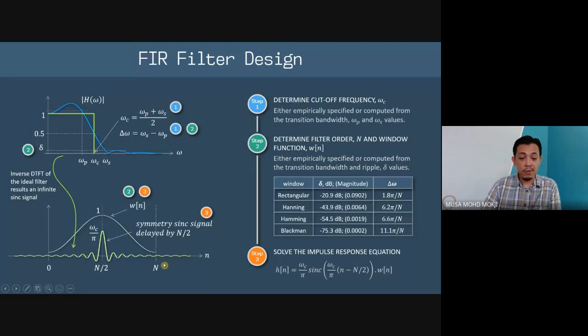So how do we solve that? We need to limit this IIR impulse response, and this is where the windowing method comes in. You have your omega n here, which starts from 0 up to n. Then we just multiply these two. Whatever value the window function has here is 0, so whatever value you have here, multiplied with 0, will be gone.